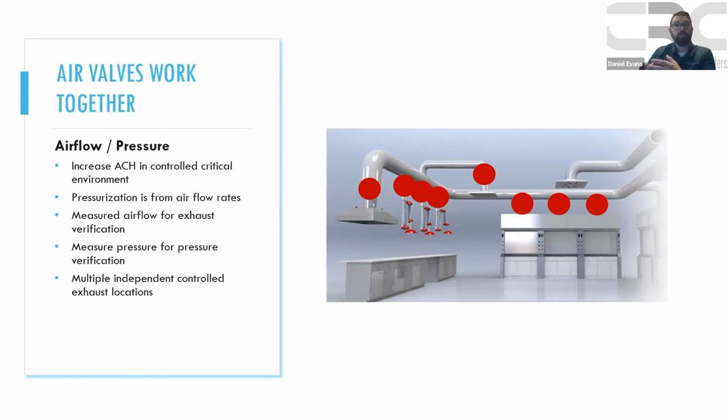And one of the areas we want to ensure, when we talk about air valves or ventilation technology, is that we pick one that can ensure all those parts and pieces are working together. We have all this exhaust come together, but what happens on the other side? We typically get into a scenario where we might only have one supply into the space. So now we're trying to maintain volume in, volume out with 9 independent pieces, 8 working together, 1 working to follow whatever happened to those other 8. That's where, in air valve technology, we talk about having that consistency and repeatability of outcome when it comes to airflow measurement, and not having things that are going to impact our interaction with the space.